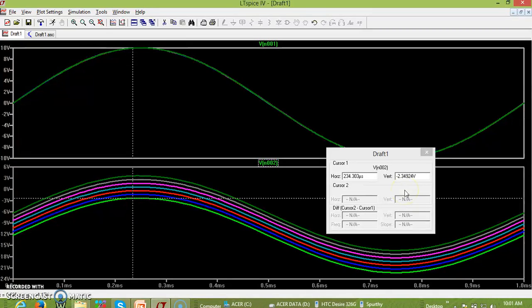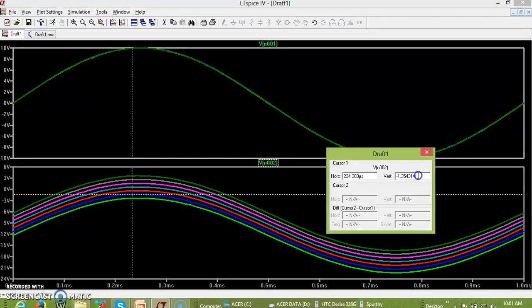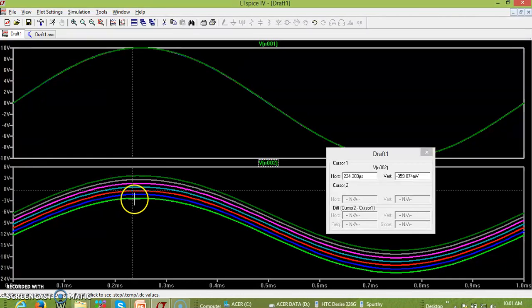So let us try to see for a reference voltage of -2 how it looks. For -2, you can see it is VD1 minus 2 volts. VD1 minus 2 volts, that is 0.6 minus 2 volt, happens to be minus 1.4. So you're getting almost minus 1.3. So this is for one more point here. So this is for -3, this is for -2, the red one is for.